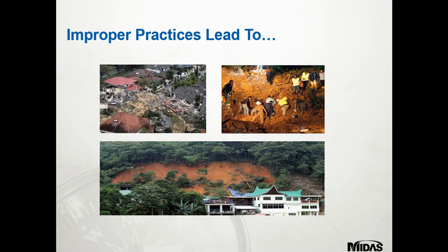So here are some pictures of some failed slopes. As you see here, obviously the one at the bottom has been created by a large amount of rainfall, and the slope has failed because the pore water pressure has filled the voids. And you've also got 2 other failure points at the top there, just some examples for you.